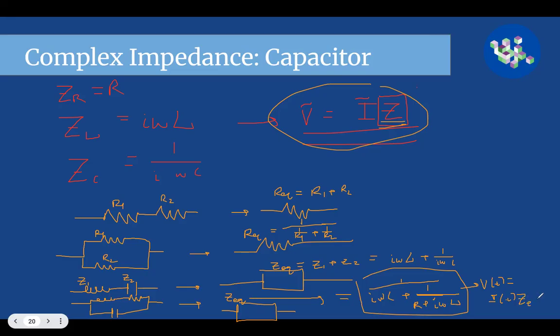It's really, really convenient because it's as if you have resistors, except you call it a complex impedance, and each different element has a different complex impedance. But the really good thing is that if you have two elements in series, the complex impedances add like two resistors in series. And if they're in parallel, it adds like two resistors in parallel. That's a really convenient thing about complex impedances, and a big reason why we invented them and why people study them, right?